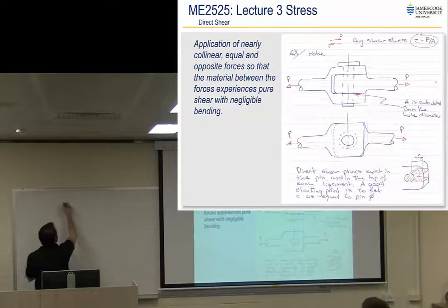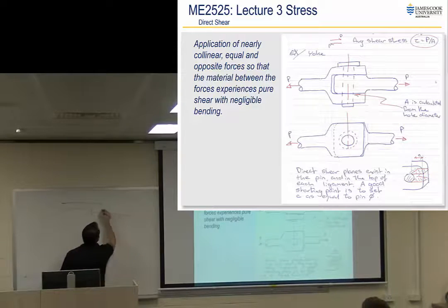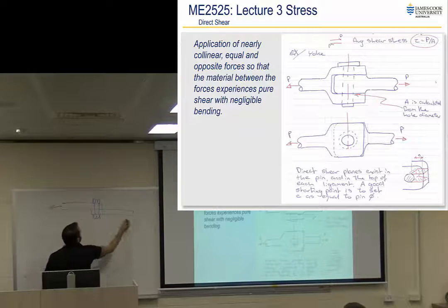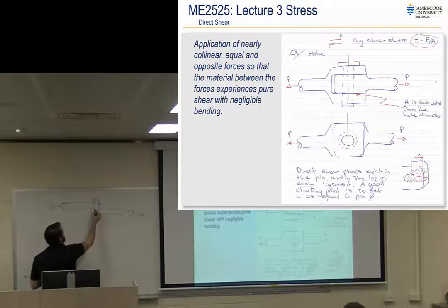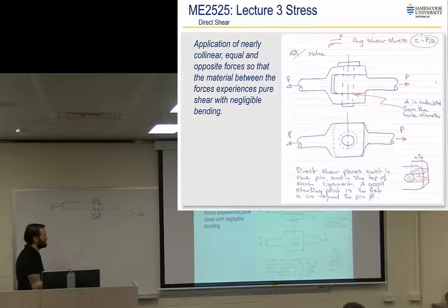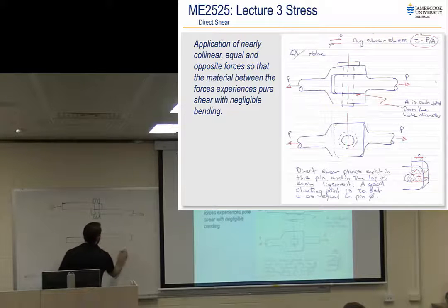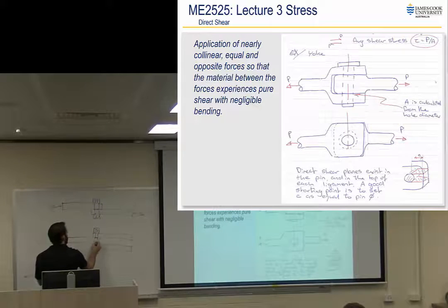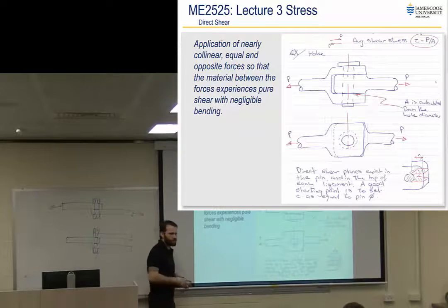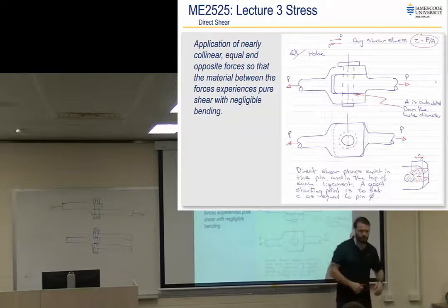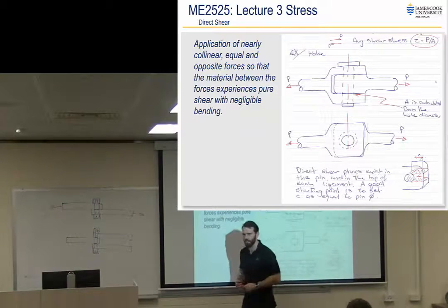All right, single shear very simply just means that single shear means you have a single shear plane on the bolt. Double shear means, like that yoke, bolt, that you have two shear planes. Which one's better for the bolt? Double. Yeah. Every single day of the week, double shear is better than single shear.